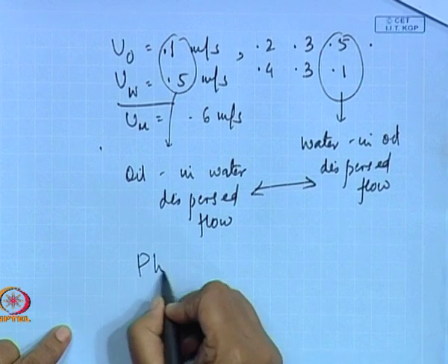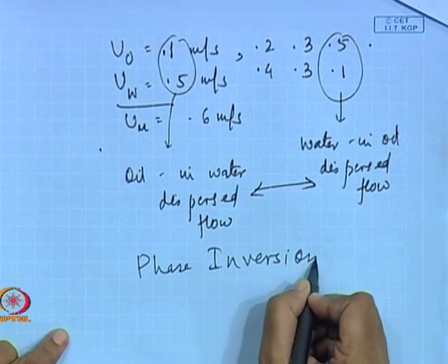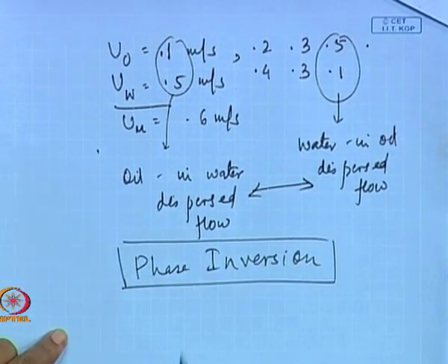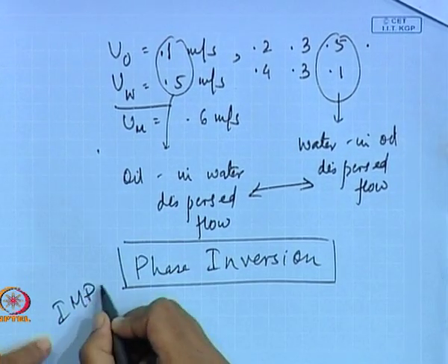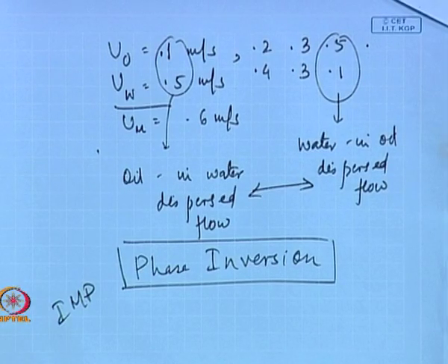For liquid cases, this word is very, very important. You are supposed to remember this: the phenomenon of phase inversion, during which one particular dispersion inverts to form another type of dispersion. This is very important, and it is usually characterized by a sudden increase in the pressure drop.